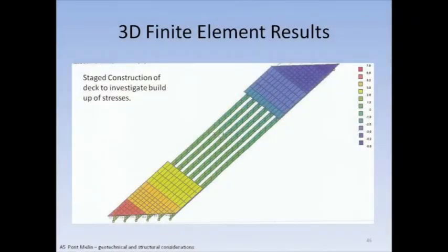And then a 3D finite element analysis was done, a pretty coloured picture for the screen. It was done to look at the build-up of stresses as the various deck elements were cast. This is between two of the deck pours. It looked at the way in which the stresses interface between the deck and the steel beams themselves.